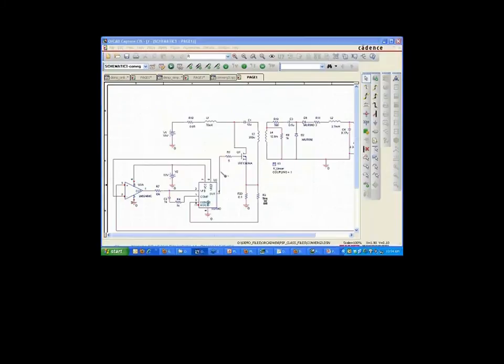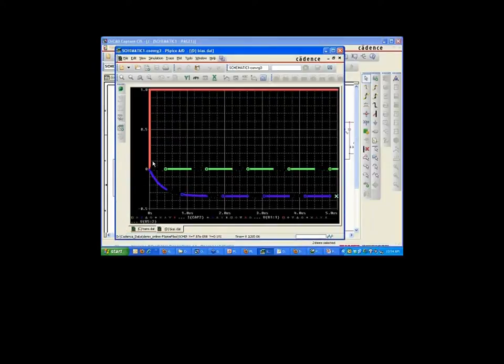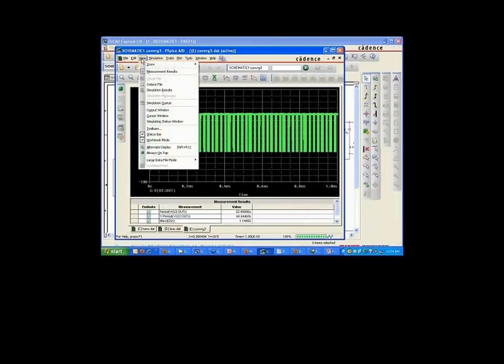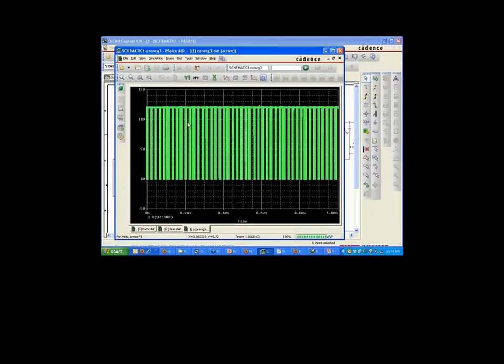And now with auto converge on, I'm going to run this and restart the simulation here. And it'll just tear through that, no problem now. You can see on the bottom here, it's just churning right through that. So 1, 2, 4, it got right through that, no problem. And I get to see some results. That's just fantastic. I get to actually see some results for my simulation, and I get to see what's going on. I'm not just stuck with text data and trying to decipher what all those non-convergence files mean. I can just get past that and see what I want to see.